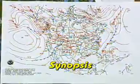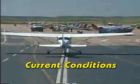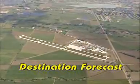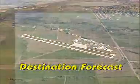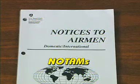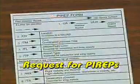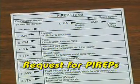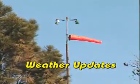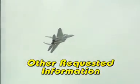an overall synopsis of weather systems, the current weather conditions, the en route weather forecast for your route of flight, the forecast for your destination airport, the winds and temperatures aloft forecast, NOTAMs, any air traffic control delays if applicable, a request for pilot reports, the availability of EFAS or FlightWatch, weather updates, and any other information you request, such as military activity along your flight route.